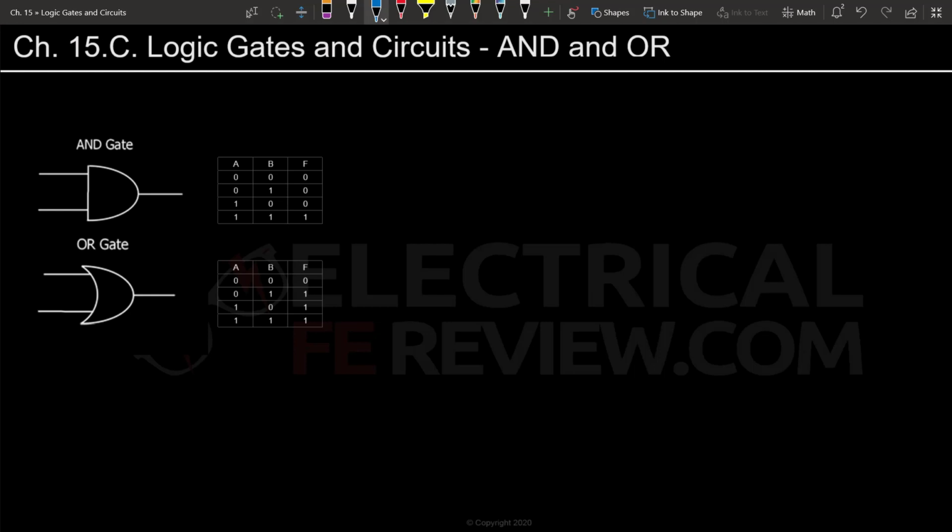I have these diagrams already ready, the AND gate, and this is the truth table. It's very intuitive to imagine it. It's just going to be on when all of its inputs, the number of inputs can be as many as you need them to be, are 1. So all of them need to be on in order to have a 1 output. So that's something definitely to keep in mind. The more inputs you have, the less likely it'll be a 1.